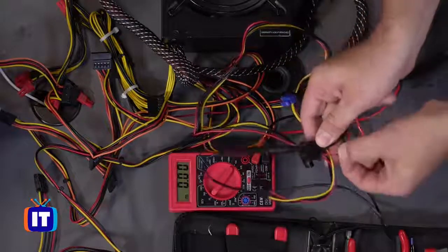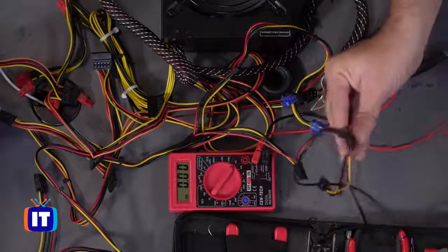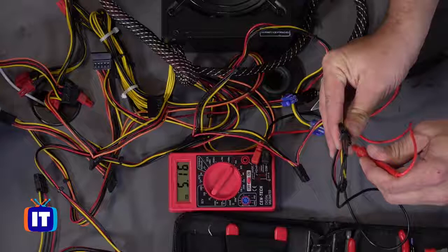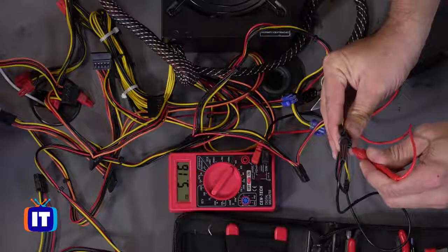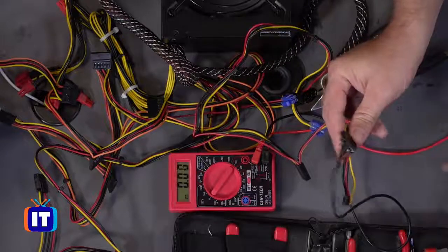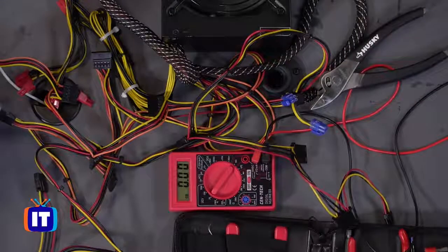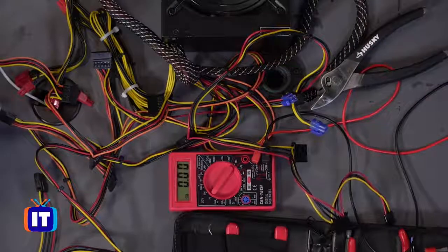and we could test again the red, right? The red is the 5 volt, or it should be 5 volts. And you can see here too, we're right in a good tolerance. So I can tell that this power supply is giving off the appropriate voltages that it needs to be, and I'll go ahead and turn this off. But that's something that you can see.